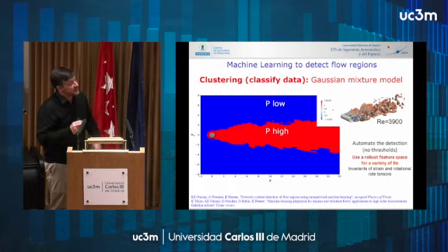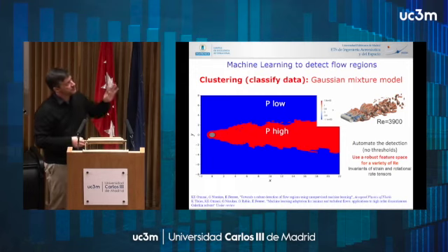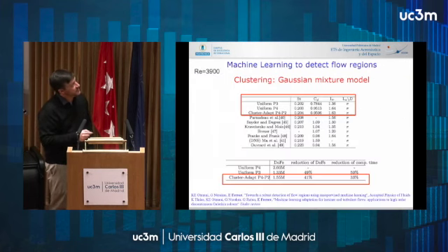We can do that by selecting the right variables, which are basically the strain rate and rotational rate tensors. We can get this interface which doesn't require any threshold or anything. You just throw two clusters and it returns these two regions, and hence we can change the polynomial order in these regions. We compare changing the polynomial to not changing it, and we see that we get the right results, of course with much fewer degrees of freedom.